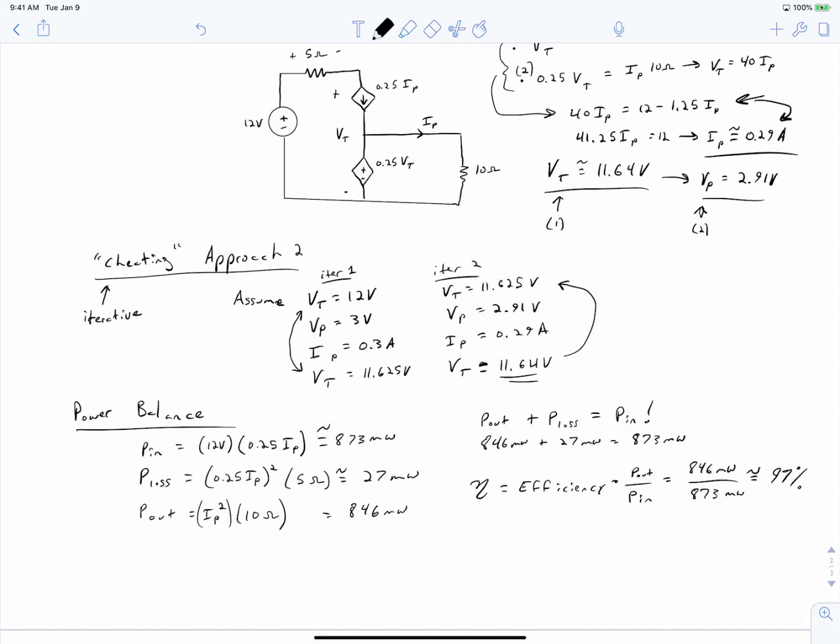So that concludes this introduction to equivalent circuit modeling of the single-pole double-throw switch. Next, we'll be talking in more detail about completing this model and considering the discontinuous conduction mode case, where our equivalent duty ratio is no longer equal to our active device's duty ratio.